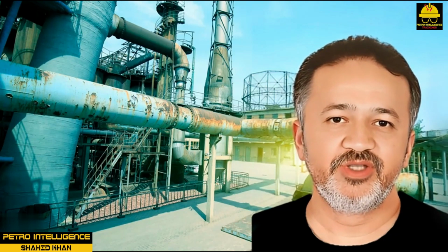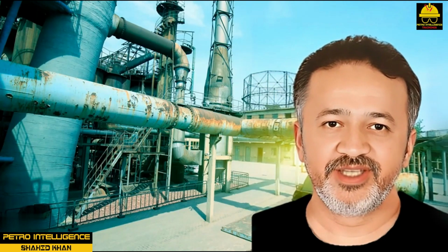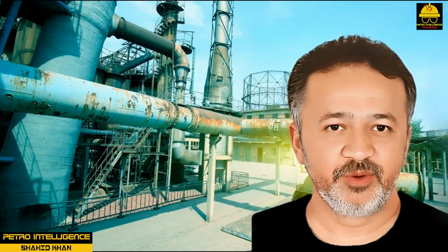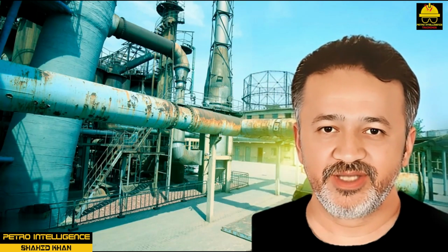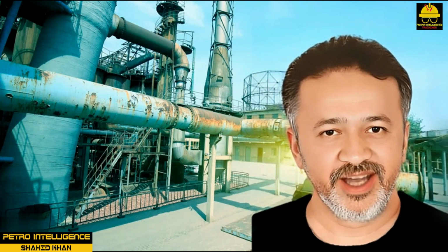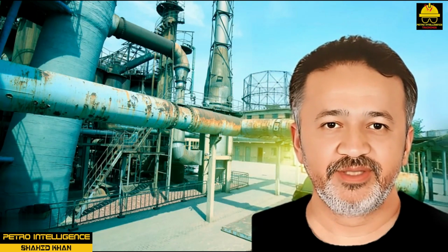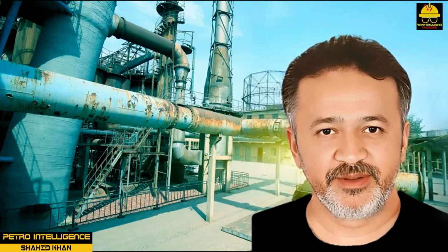Utility systems are the combinations of equipment that are used to provide a plant with water, fuel, air, nitrogen, electricity, refrigeration, and other substances or processes it needs to operate. In general, utility systems either separate materials into pure or relatively pure products or distribute supplies to the plant's units in usable amounts, store supplies, and remove waste products. Water systems include raw water and fire water systems, boiler feed water treatment systems, cooling water systems, and steam systems.